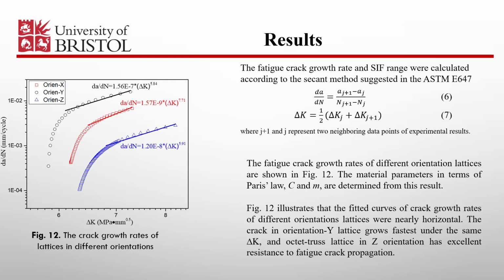The fatigue crack growth rate and SIF range were calculated according to the second method suggested in the ASTM. In the second method, crack growth rate simply involves calculating the slope of the straight line relating adjacent data points on the a versus N curve. The fatigue crack growth rates of different orientation lattices are shown here. The material properties in terms of Paris' law are determined from this result.